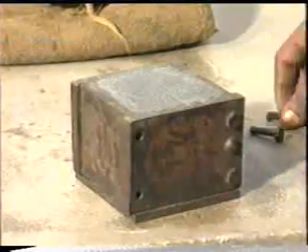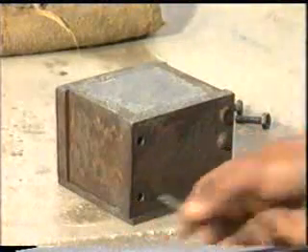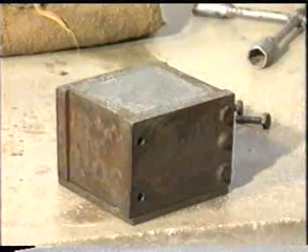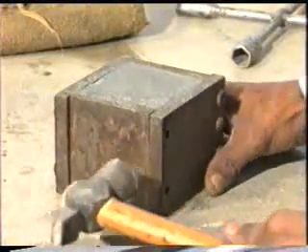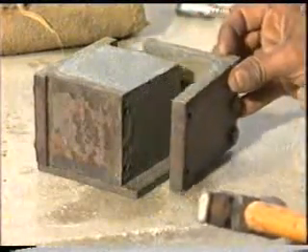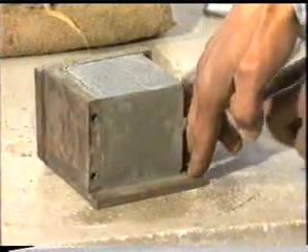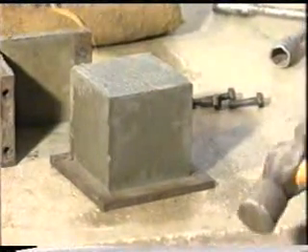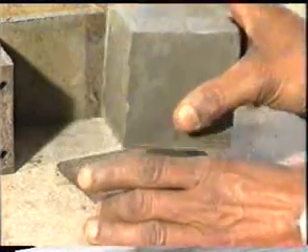The mold is then dismantled to dislodge the cast cement cube. A gentle tap with the hammer on free ends helps in the easy removal of cube without damaging its ends. The other two cubes are also removed from the mold in a similar fashion.